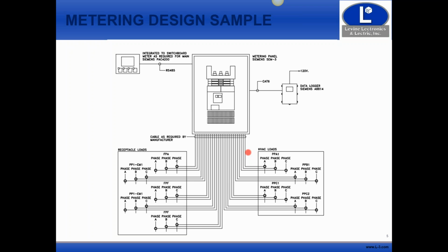From a commercial standpoint, that is true in houses. Residential, yes, you can have that all the time, and 9 times out of 10, that's the way it's done. From a commercial standpoint, the engineers usually have separate circuits. Your receptacles will be on one, your lights will be on a different one. A lot of times it's easier from a wiring standpoint that way, and it's easier from a lighting controls standpoint as well.